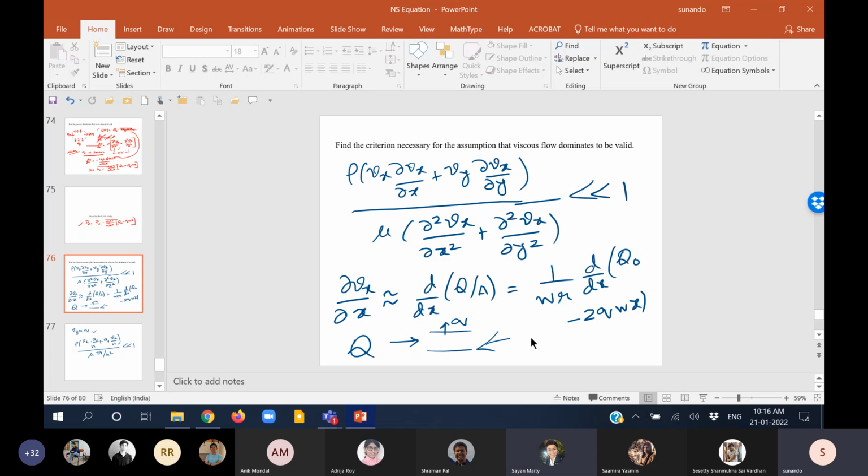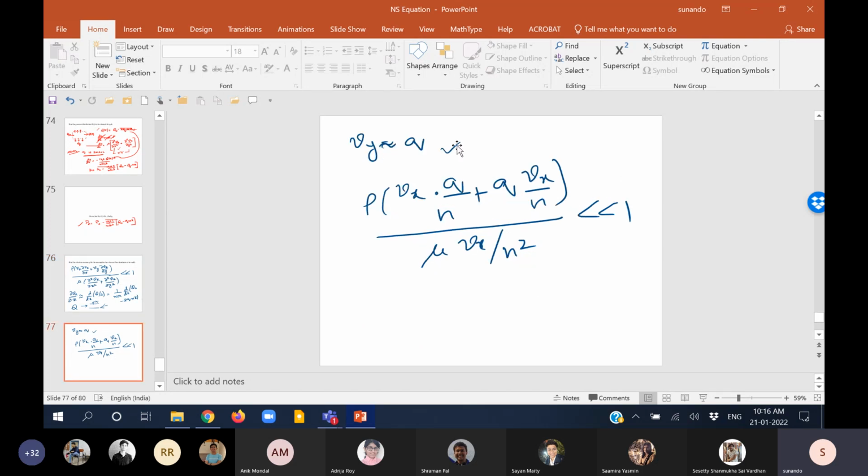Reynolds number, right? And what kind of a Reynolds number is it? Is it the flow Reynolds number which is related to capital Q, or is it some sort of a Reynolds number which is related to small q? Which Reynolds number are we talking about here? Related to small q. So the analysis of this would provide you, and I leave that to you, that rho small q h by mu has to be small.